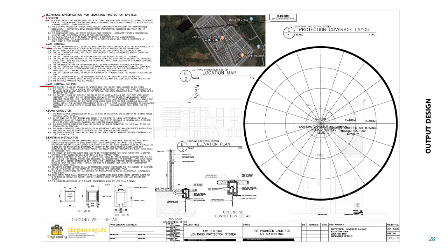These are part 1 of our projects. Then this is the part 2 also of the design, so the protection coverage. This number 1 is the protection coverage. This number 2 is the air terminal, and the terminal support is for the mounting structures. The down conductor and the earthing is for our grounding, which is already defined.